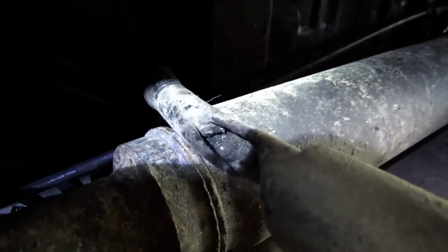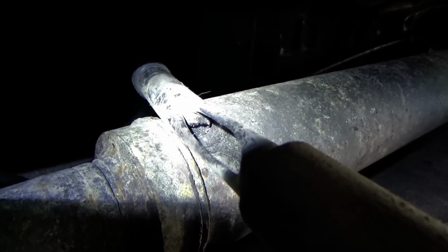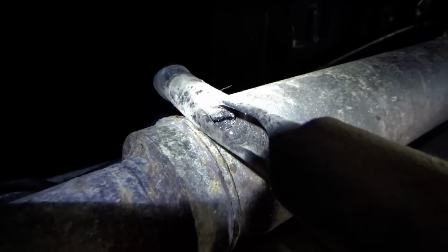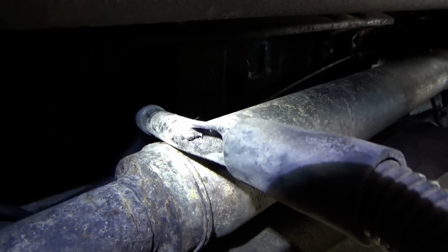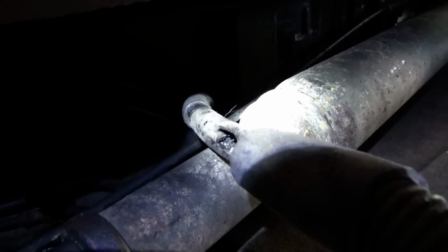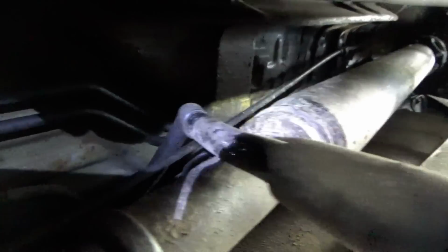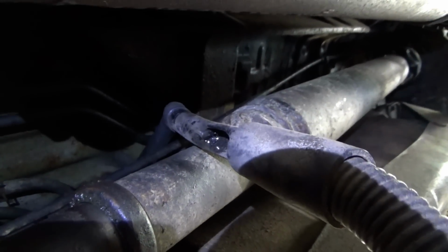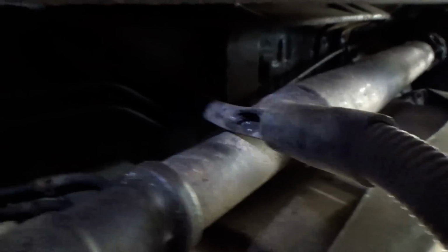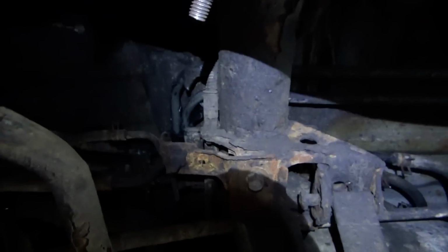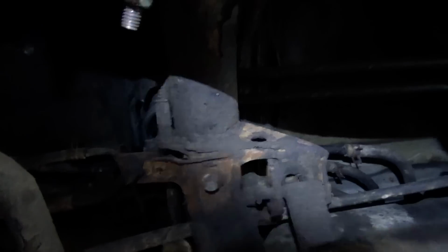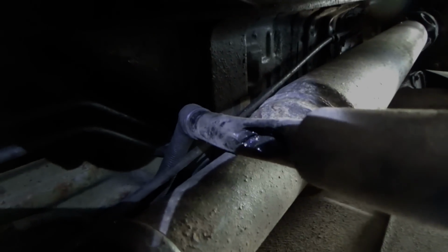I disconnected the vent pipe from the canister, and bingo, this sucker melted and actually shut the whole pipe. Amazing. That's it. That explains all the customer complaints. So we need to fix this, and we need to replace that clicky valve, and then it should be good to go. So I'm going to take a picture of this and tell the owner to listen to the mechanic's recommendations when they tell him to fix the exhaust, because driving around, especially in the summer, with hot exhaust gases blasting at your plastic pipes and wires, that cannot lead to good consequences, as shown here.